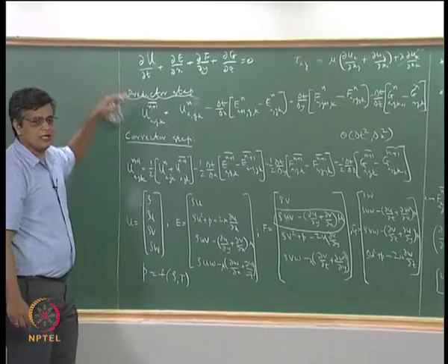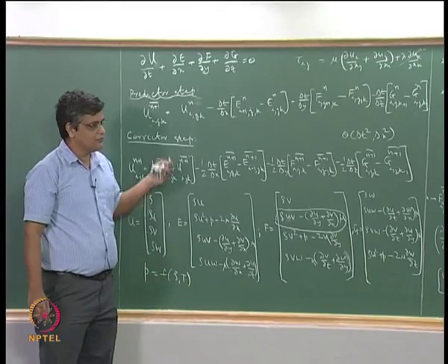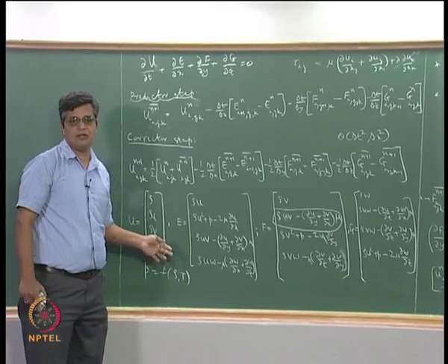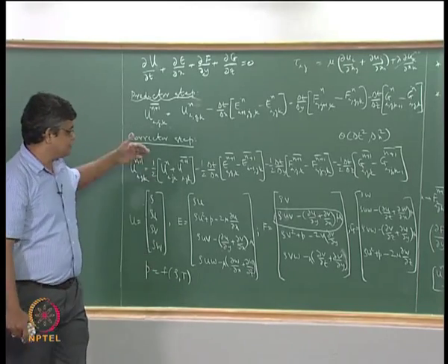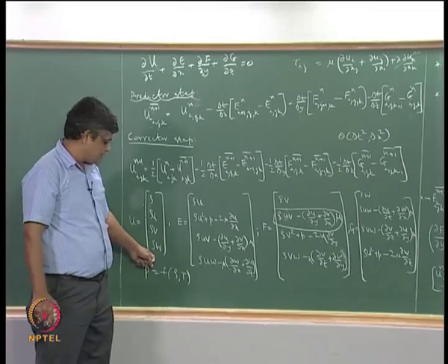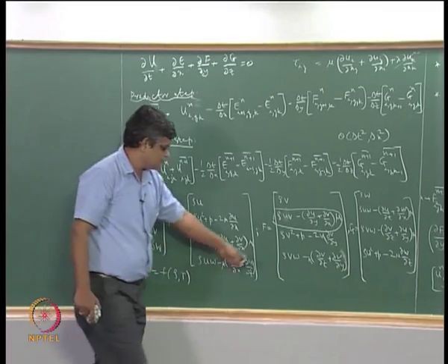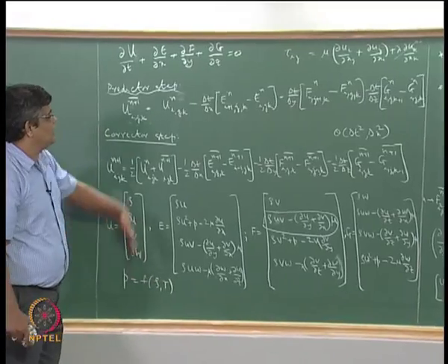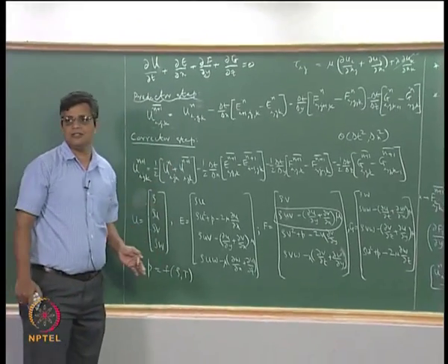And we have assumed isothermal flow here, but for a general compressible flow we will have to also solve for the energy equation, which we have not derived yet, and the incorporation of the energy equation to the calculation is very straightforward. We will have an additional variable here and additional set of terms coming in the energy equation, and those can be solved together with this.